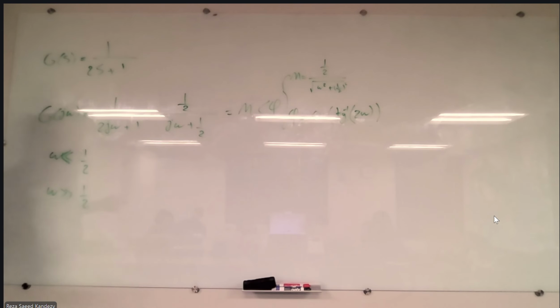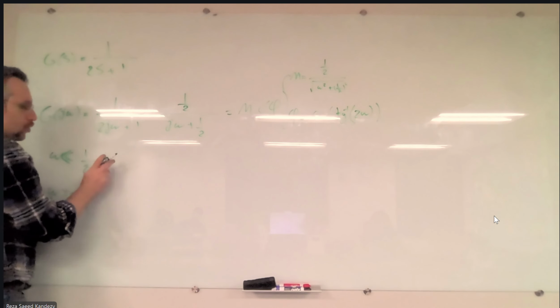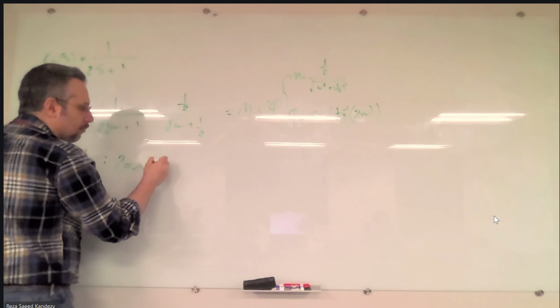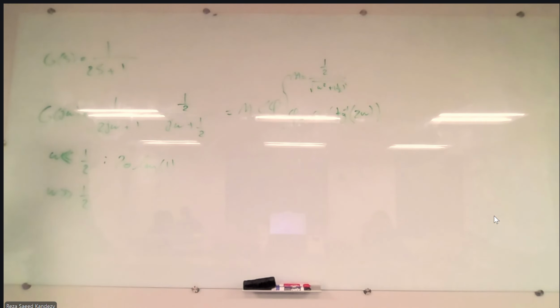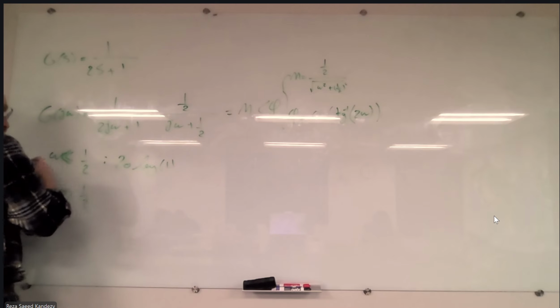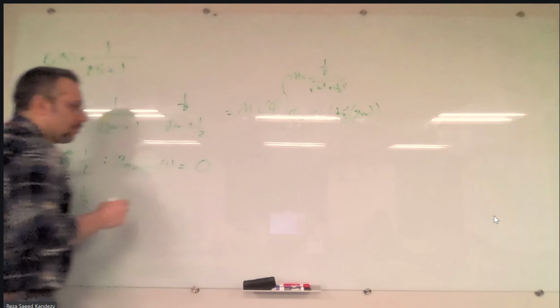Now, we want to show that as a decibel value. So instead of simply saying M, we want to show the magnitude as 20 log of that M, which is 1 in this case. Are we good? Now, 20 log of 1 is 0, because log of 1 is 0. So, if we are below 1 over 2, our magnitude Bode plot is going to be 0.